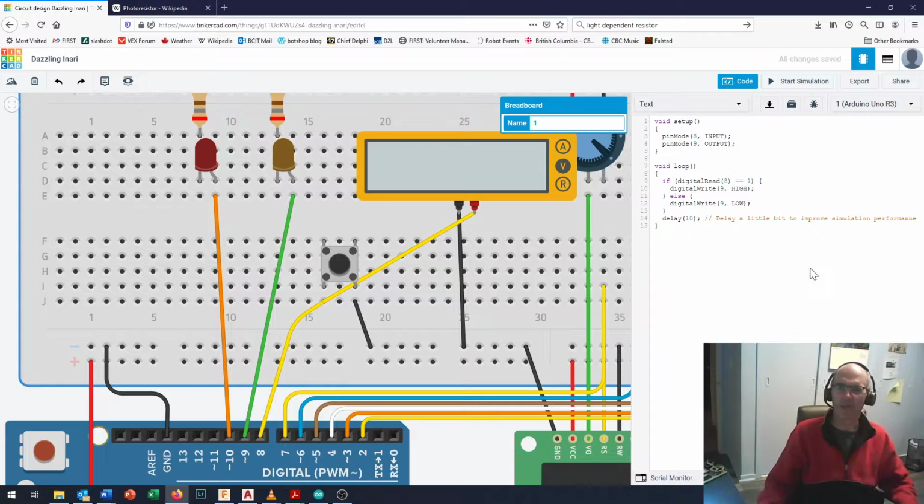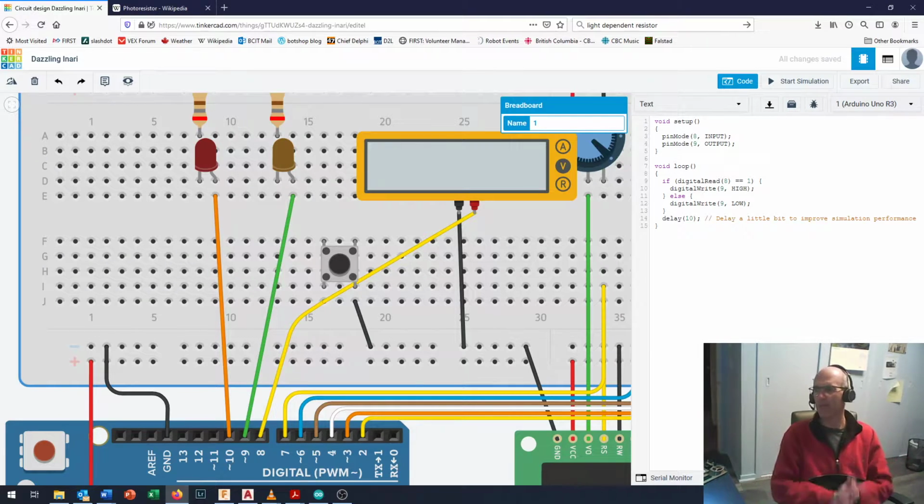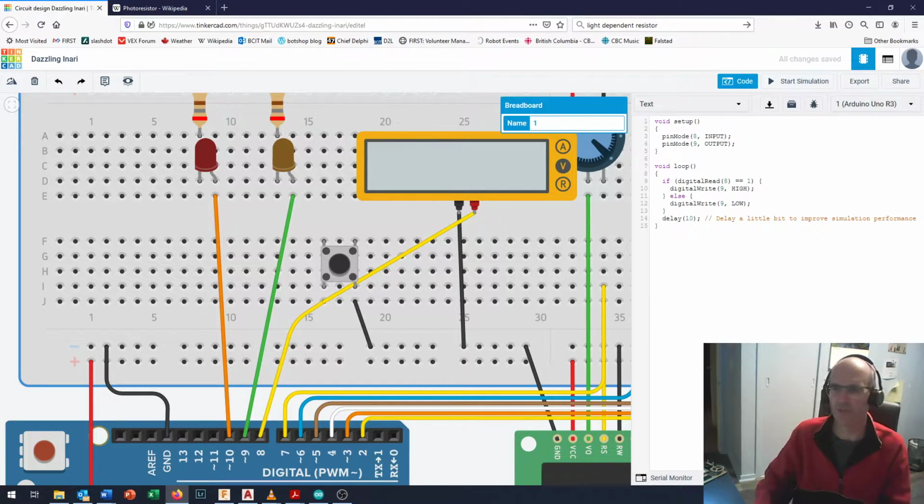All right, so now I've kept the code, and now we're typing code into the computer. And we can edit it manually. And so if we don't want to put a real genuine pull-up resistor onto the board, we can say input, and then we go underscore and pull up, all in capitals. And what that does is inside the Arduino chip, it comes along and it turns on its own internal pull-up resistor. Okay, there's no such thing as an output pull-up resistor because you're actually controlling what's on the outside of